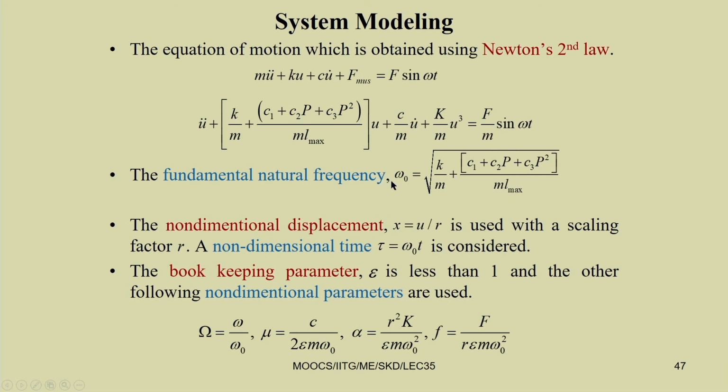You can notice that the natural frequency of the system can be varied by changing the muscle pressure. So, by changing this pressure P, we can actively control the frequency of oscillation. By controlling the natural frequency we can always avoid the resonance condition, keeping the resonance frequency away from the natural frequency. Or whenever required, we can control the muscle pressure and bring the system to resonance so that we can have maximum displacement.